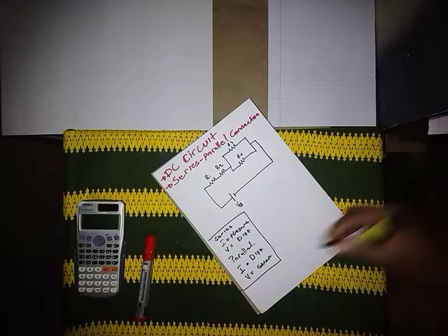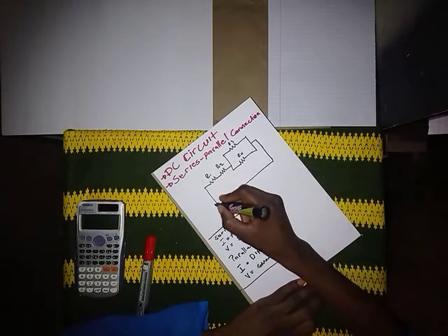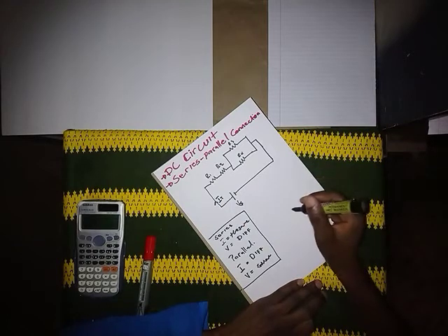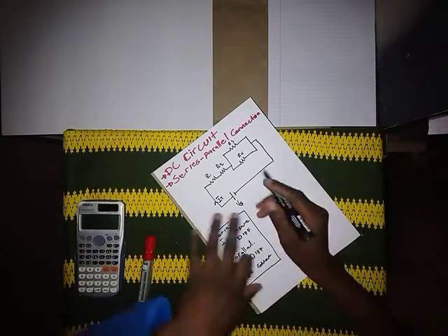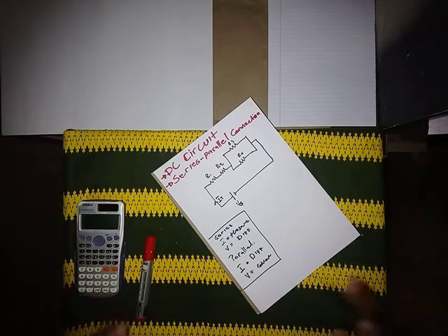Now when our circuit is closed, the current IT will flow in the circuit. This is how you analyze your circuit. You look at the flow of current, and if the same current is passing through two or more resistors, that means those resistors are connected in series. But if the current is splitting, and the resistors are getting different currents, that means those two branches are parallel.